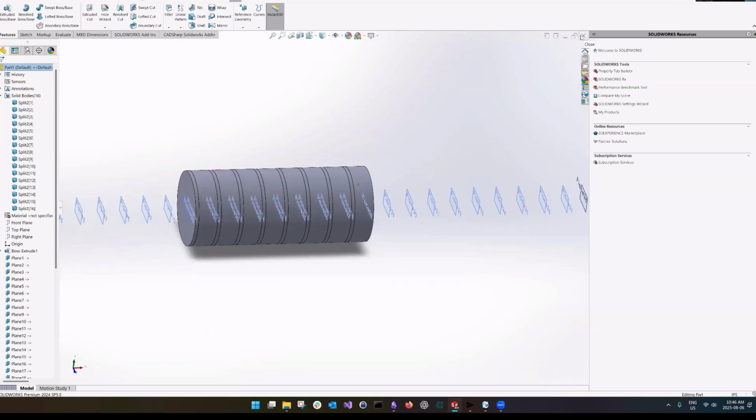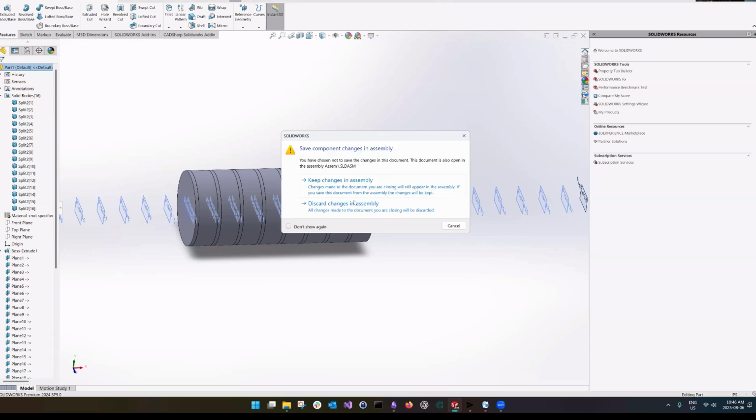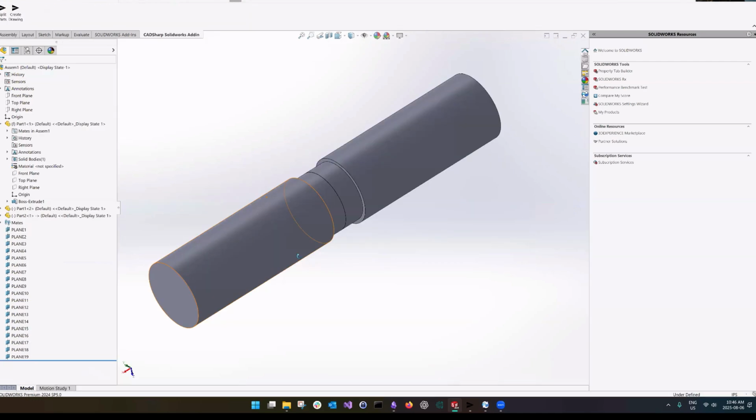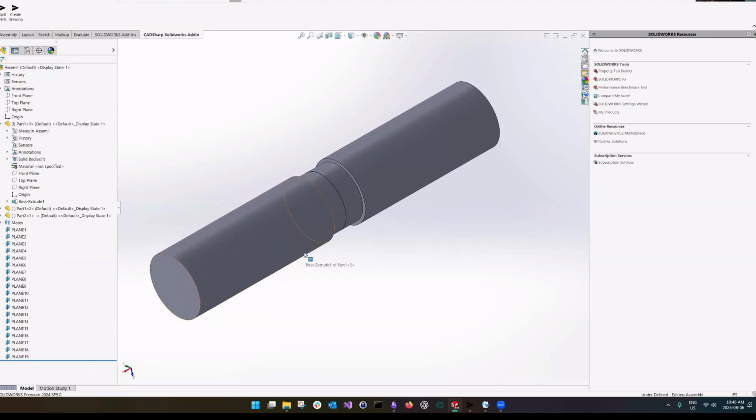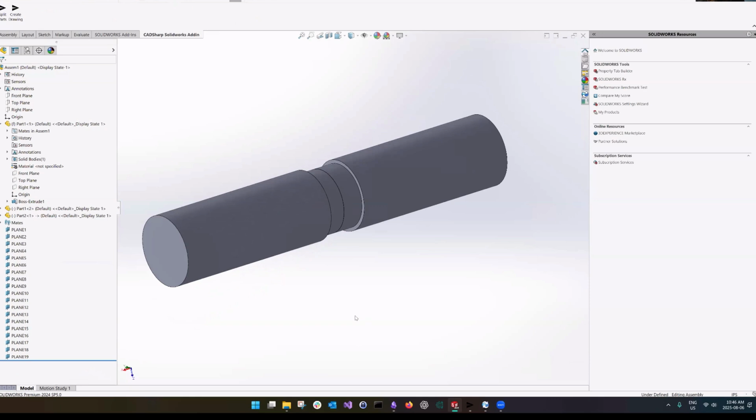This is just an example to show what we can do. We can manipulate geometry via these property manager pages. But a real use case for something like this is calculating mass properties across a section. So if you had a complex shape like this and you need to do some analysis, you could then section that and then calculate mass properties for each body and then plot them.